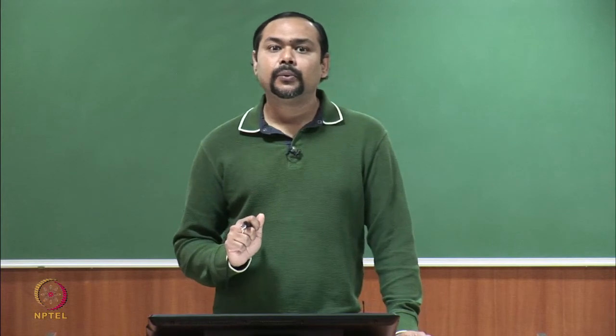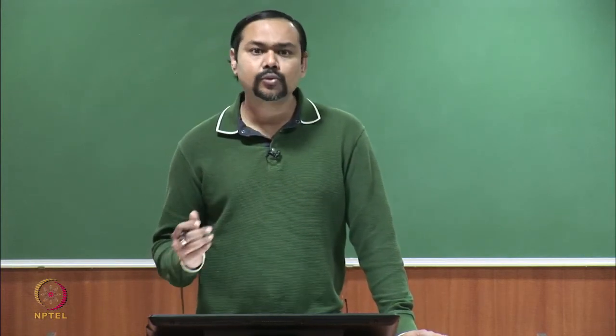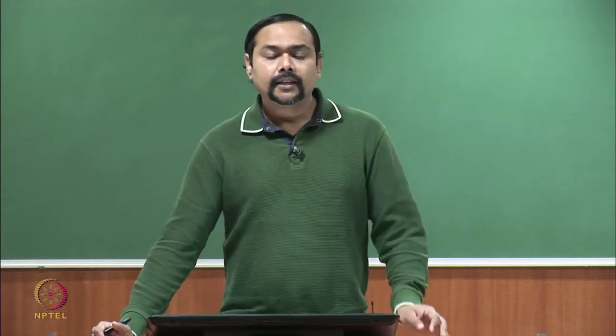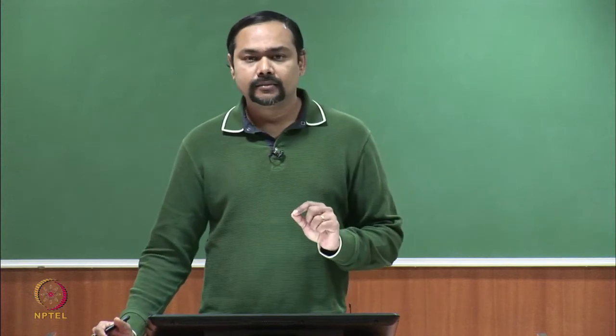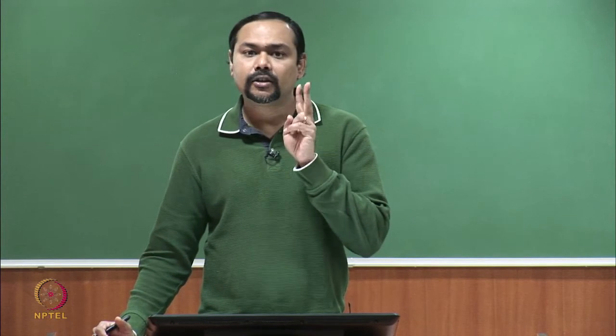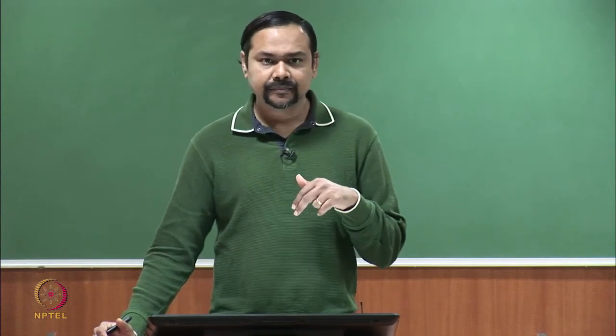This is something which was not present in a two level space vector diagram. It was in fact present, but only for the 0 vector. For the 0 vector, if you remember, the 0 vector had two multiplicities, plus plus plus or minus minus minus. Okay.